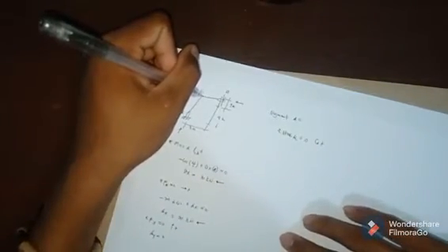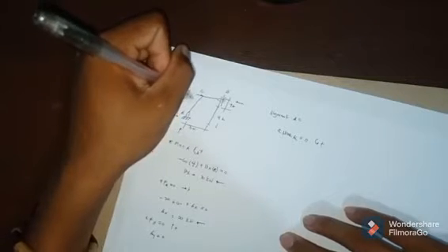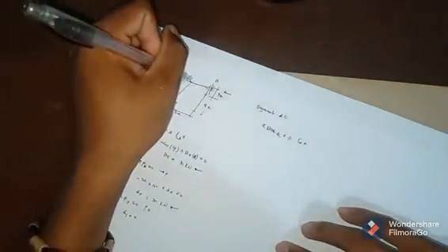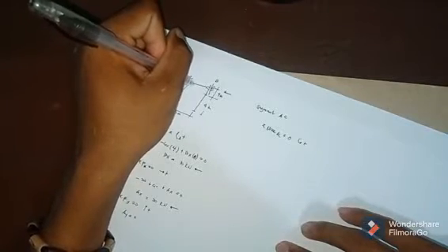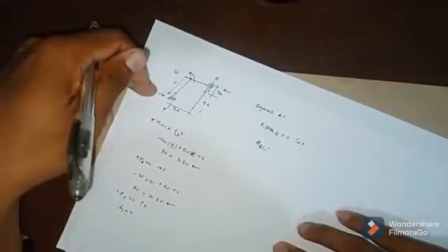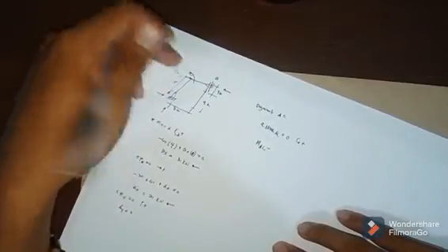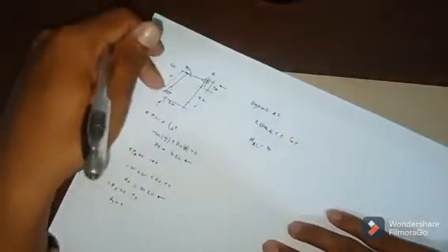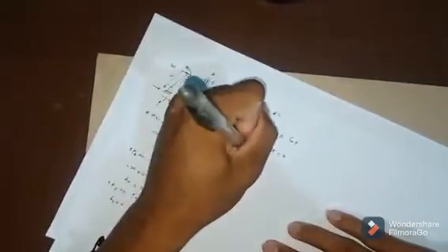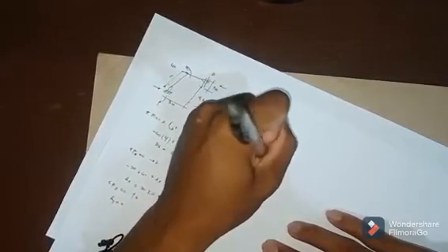If we take the moment here, we label this as x, so the moment is rotating counterclockwise, so it is positive. So moment AC, positive, minus the horizontal reaction, which is 30, and the perpendicular distance, which is x, equals 0. So moment AC is equal to 30x.